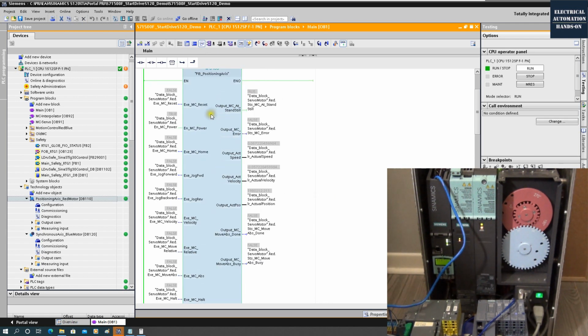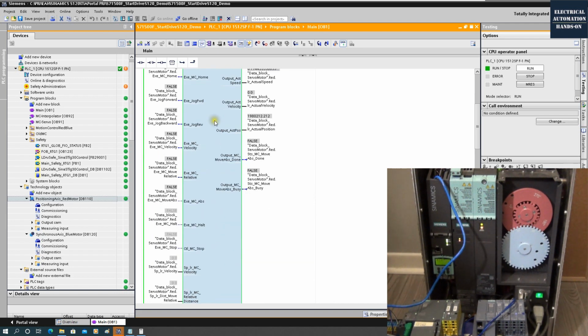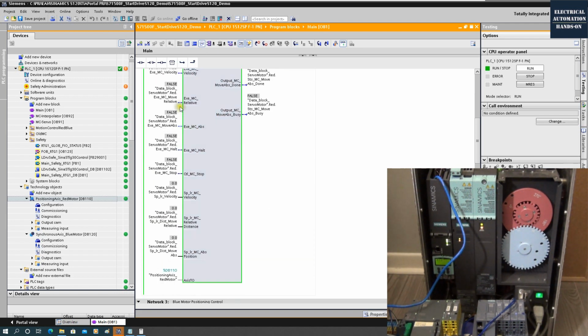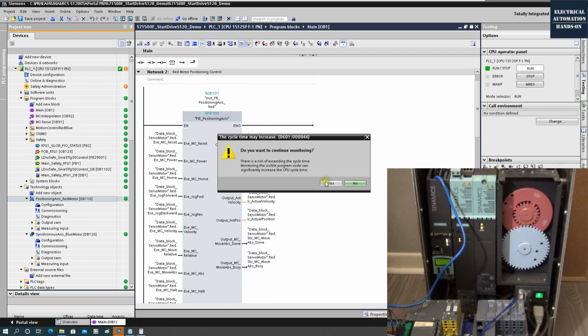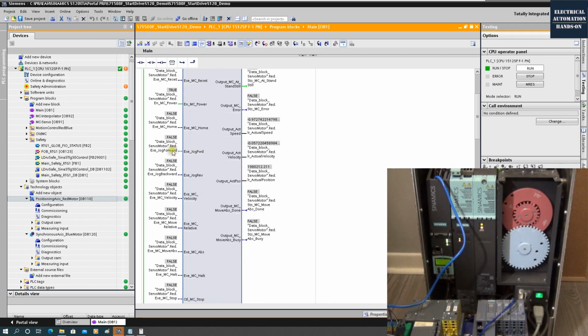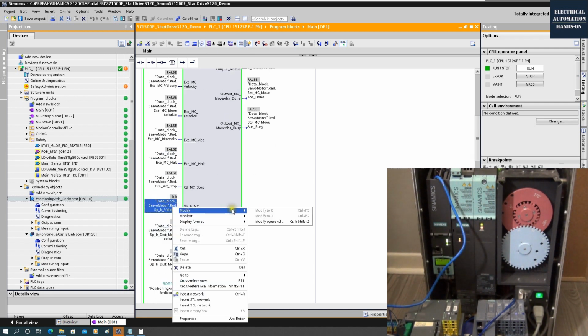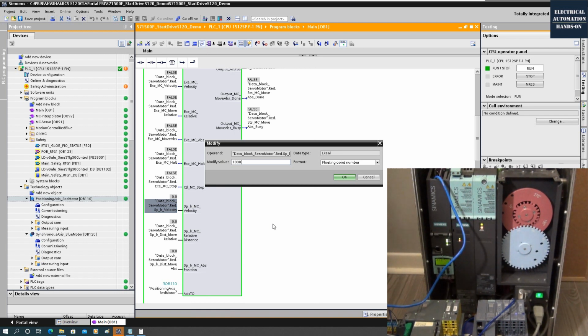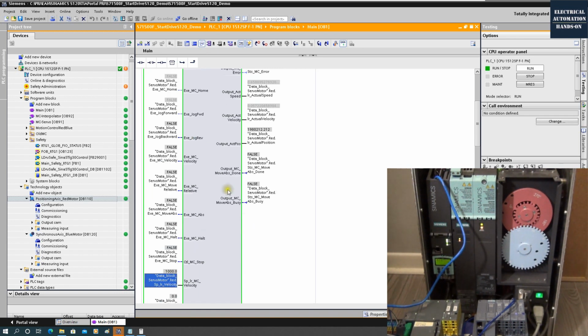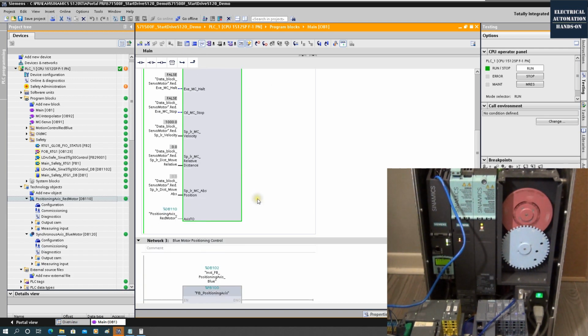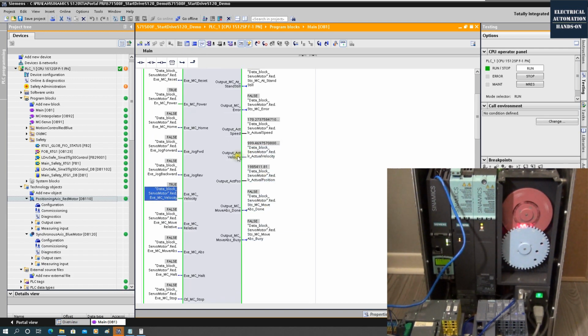And now I will fire this red motor using the velocity control. So velocity, MC velocity. Okay, so the MC velocity and its set point, I can set 1000. Okay, and now if I fire this motor, the red motor is now running. And from here we can see the red motor speed is now 1000 degrees per second.